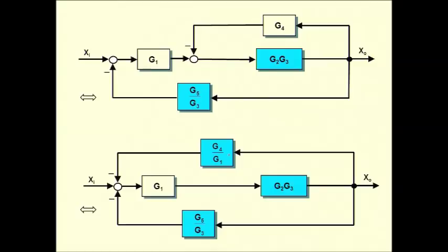And then I did something differently. All right, well, there are two ways to solve it. Like I said, you could look at that and simplify this first. But what I've actually done is move this summing junction over to here, this one over to here to combine it with this one. And when I did that, I needed to divide by G1 in this transfer function. Look at the rules if you're not sure.